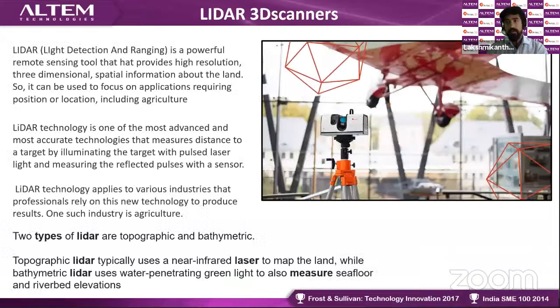So today we'll mostly talk about the lidar section. As everyone might be aware, or for those who are very new to this, what is a lidar based measurement system? Lidar is light detection and ranging. There will be laser scanners mounted on some equipment, either on a tripod or on an airborne device. It projects light patterns, and whatever reflection happens is calculated, and it recreates the entire scenario. So it is just like a 3D scanner, in one way or another.